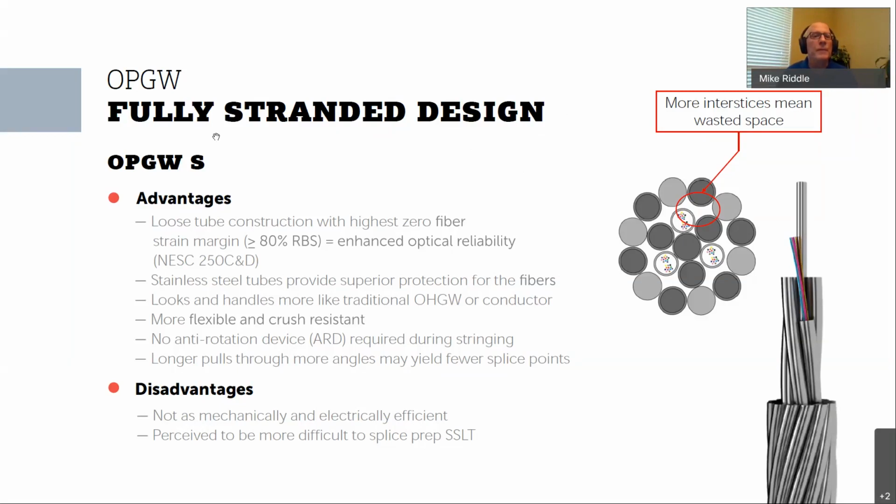So picking up with the fully stranded design, again, loose tube construction, the highest zero fiber strain margin, and that means that you can meet NESC 250C and D rules, no problem. Again, I've talked about it, the stainless steel loose tubes provide good protection.